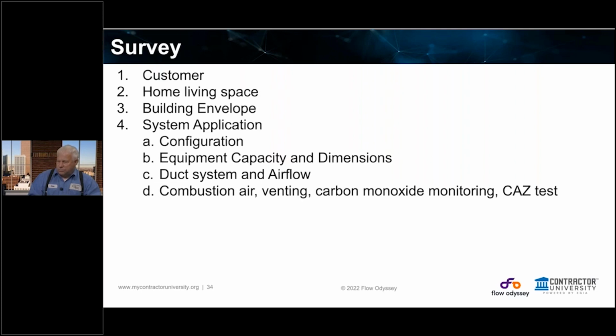Correct. Okay, and let's talk about that real quick. Carbon monoxide detectors versus carbon monoxide monitors, right? The things that customers can buy at Lowe's and Home Depot and Costco and online, those are carbon monoxide detectors that they can get at retail. And like Eric said yesterday, those things start signaling anywhere between about 60 and 70 parts per million. That's so that they can get the UL listing, which is an electrical listing here in the States that makes it safe and certified, right?